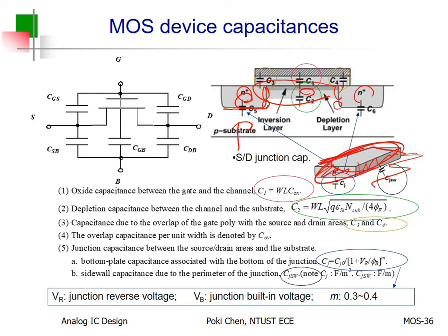But for such kind of parallelepiped, it has 6 faces, right? So how about the top one? Does it have any kind of PN junction? No. You have N inside. Yes. And how about above it? Silicon dioxide. No P-type semiconductor. Got it? So we have only 5 faces with parasitic capacitance.